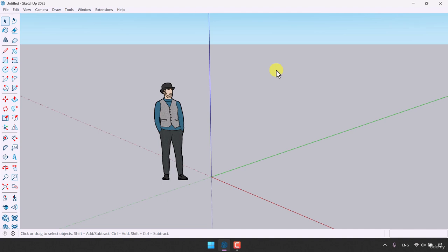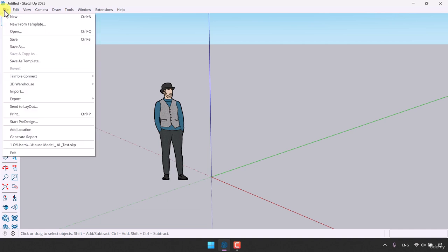Another point is that we have these windows and parts in here. I'm going to start with the File option. We can create a new file and you can see the shortcuts in front of them, for example, Ctrl+N. Then there is New from Template. The difference is that when you click on the new file, the simple default template will be opened for you.